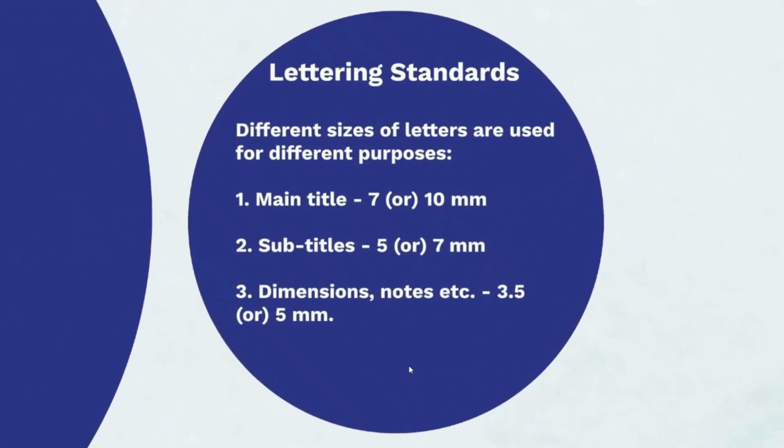The next letter standard we are going to see is that different sizes of letters are used for different purposes. For example, the main title should be 7 or 10 mm only. The subtitle should be 5 or 7 mm only. The dimension notes and everything we write in small case should be 3.5 mm to 5 mm only.